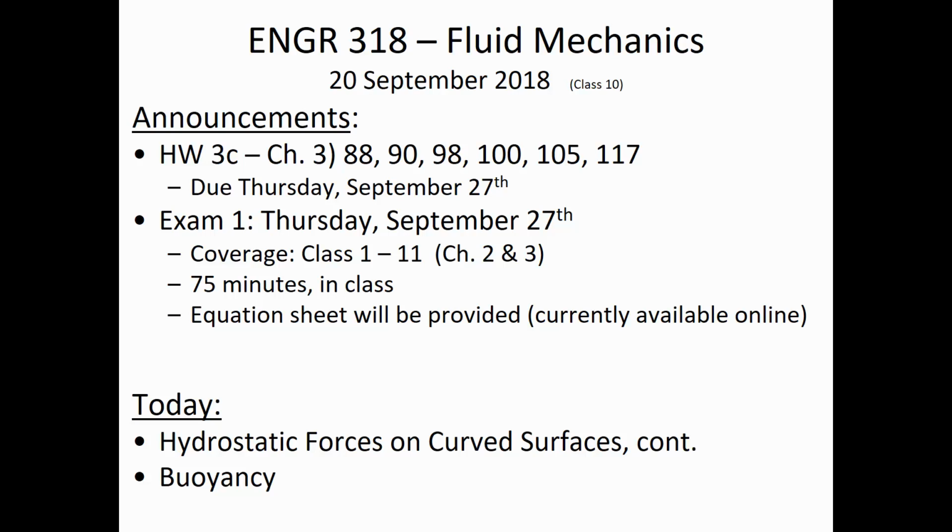So force magnitude is what for the horizontal forces? The vertical projection. Okay, good. So for this curved shape, we have to prepare a vertical projection. If it was a hemisphere, then the vertical projection would look like a circle.